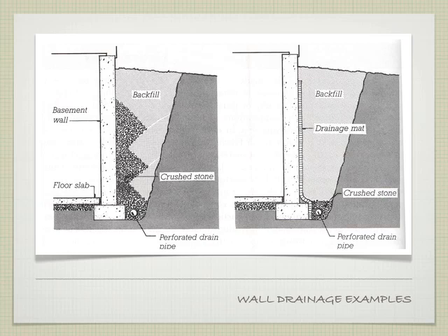It's cohesive soil, right? It would be clay, something like that. So we have this. We cut this down. We put in our footing. We put in our wall. When we go to backfill, we put a drain pipe in first, followed by a bunch of rock supplemented with the backfill, and when we get to the top, it's more of just the soil itself.